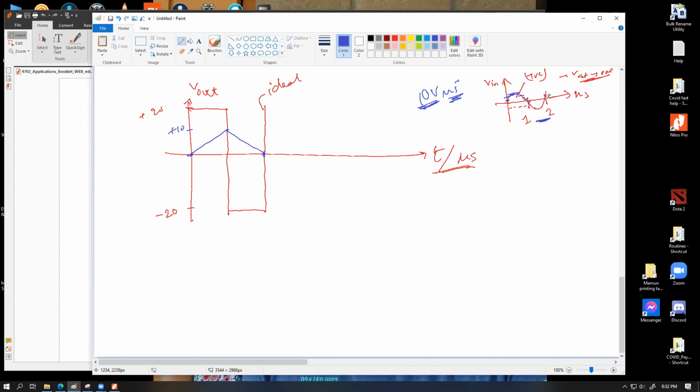this input will once again become positive, which means it will no longer have the incentive to go negative. It will once again start to go positive like that. So in this case, we are not going to have a negative output whatsoever, because the op amp cannot handle that much high frequency. A 1 microsecond, 2 microsecond time period means an extremely high frequency.